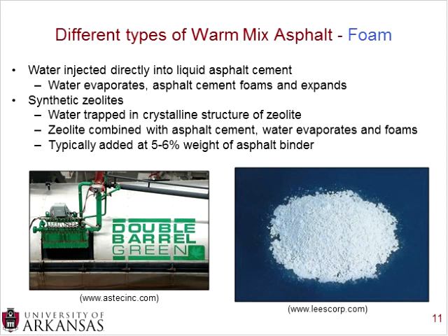The other alternative to the foaming technologies are synthetic zeolites. And this is where you have water trapped in a crystalline structure. The natural form is in a zeolite, but then you simply combine these zeolites with the asphalt cement. So it's just kind of like a wet additive to your asphalt cement. And when that happens, the water that is trapped in the structure evaporates, and that causes the foaming mechanism. Now when you're looking at synthetic zeolites, this is an addition of another product, and it's approximately added at 5 to 6% of the weight of the asphalt binder.